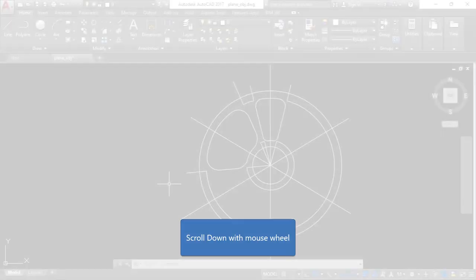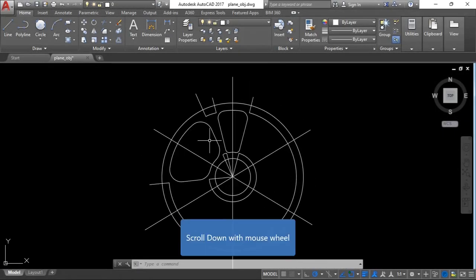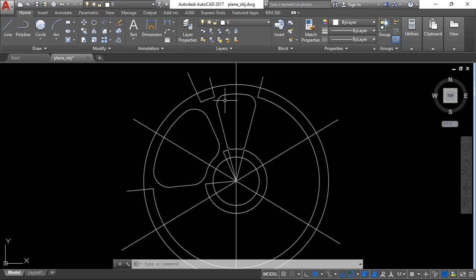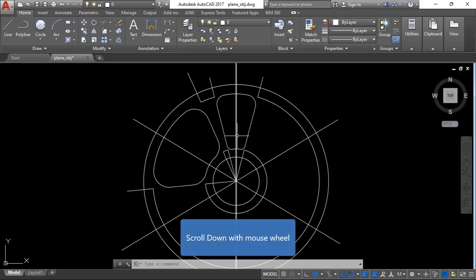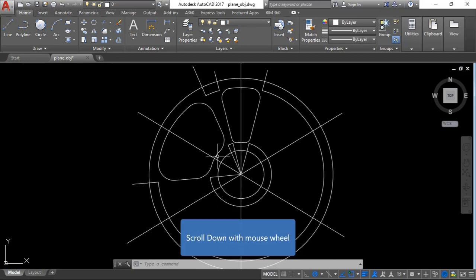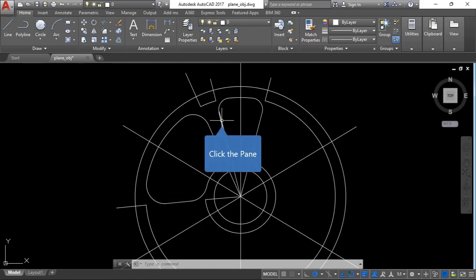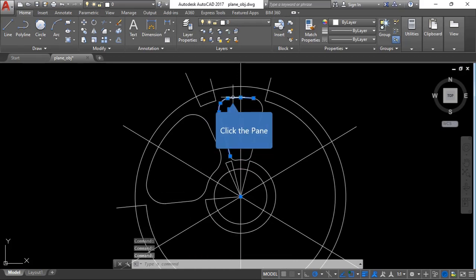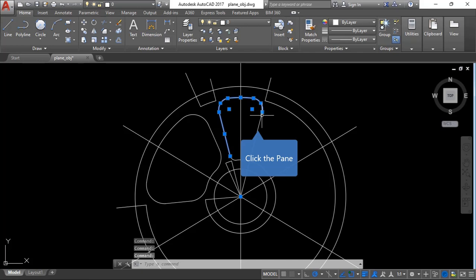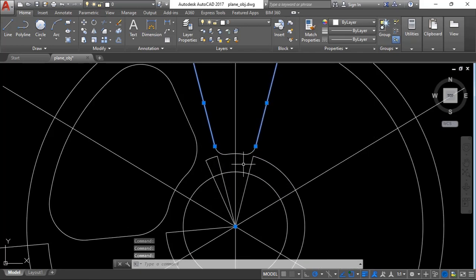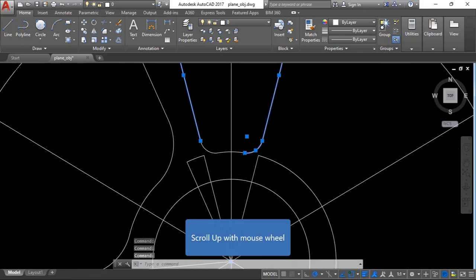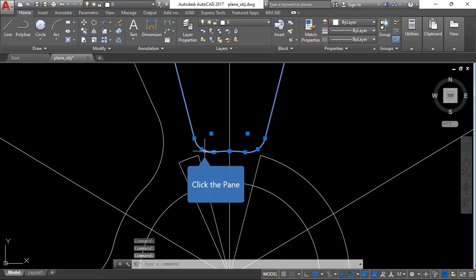Okay, all right, so now what we're going to do is to copy these shapes to the other positions that we are interested in. That's very easy. We just use the copy command, simply type CO, but first you need to select the lines that make up the object that we want to copy.